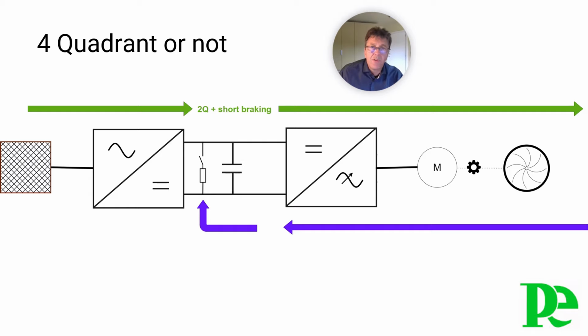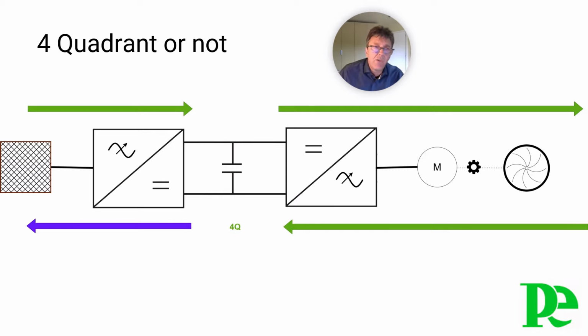Applications that do impose important power flow from the machine to the motor are classified under special purpose. In case of VSI topology, these applications require an active front end, allowing recovery of the energy to the grid for four-quadrant operation. However, the two-level series-connected multi-level cascaded H-bridge cells drive topology cannot provide four-quadrant operation. On the other side of the spectrum, the PWM-CSI and the LCI are inherently four-quadrant drive topologies. Typical examples for this use case are large inclined conveyor belt machines and test stands with the power drive system simulating the load of the tested machine.